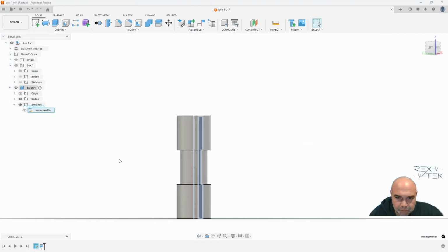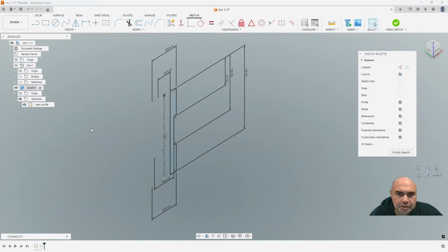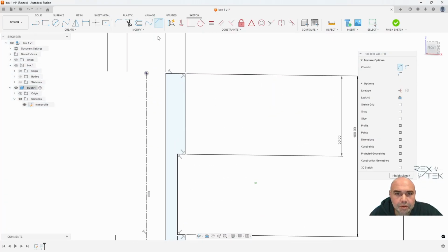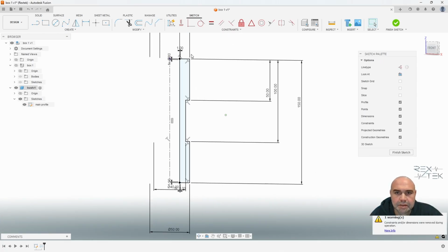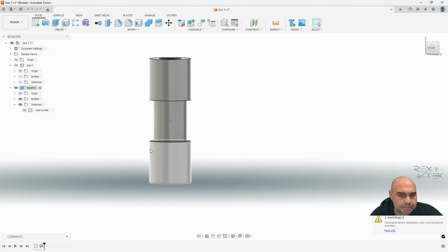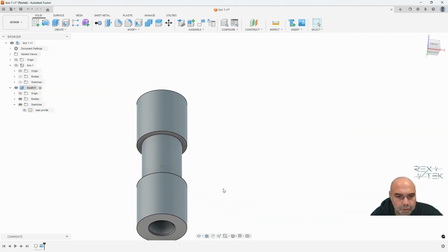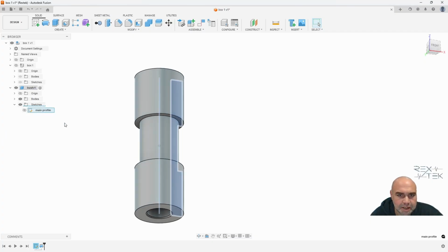So now to add chamfers, we could have put chamfers and fillets in the sketch. If I double click the sketch, go back in, I click the chamfer tab, put one there, say 1 mil, one there, hit enter. Just put my chamfers in on there. The problem with that is, well, it's not a problem, because if it's supposed to be there, it's there, but we've put them in, they belong to that sketch.